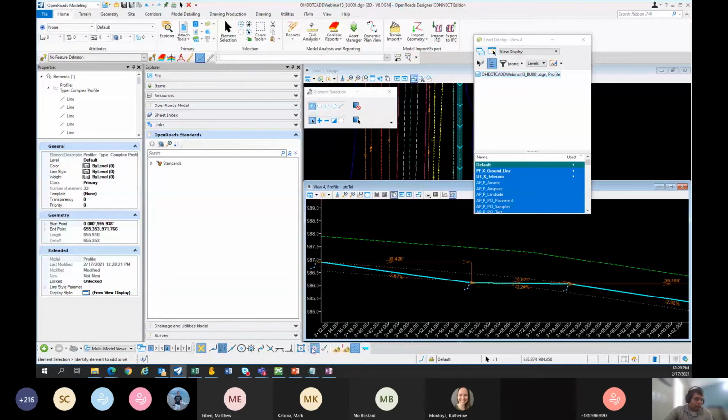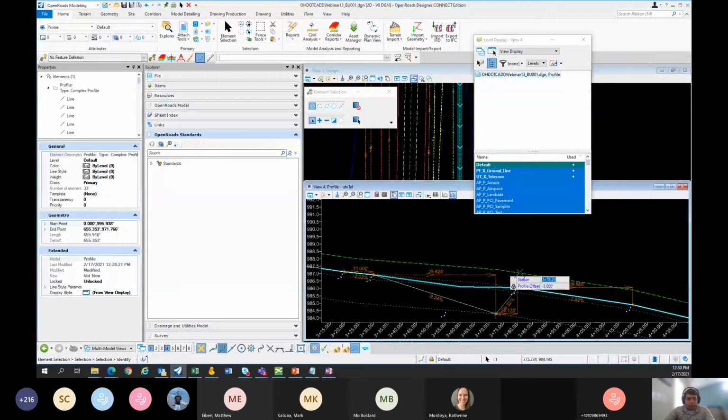But anyways, if you wanted to use the civil AccuDraw with it, you can come here and click on this point, and you see how it pops up that civil AccuDraw properties. So if I hit the O key to set the origin, I want to hit the C key for the civil origin. I can let go of my mouse now, and I have to do that again, O, C, and now I can select that as my reference, and I can put it offset. Maybe I know it's 3 feet, so -3.